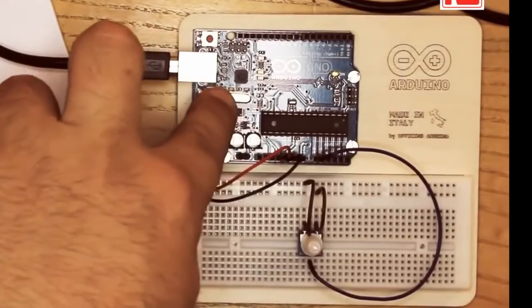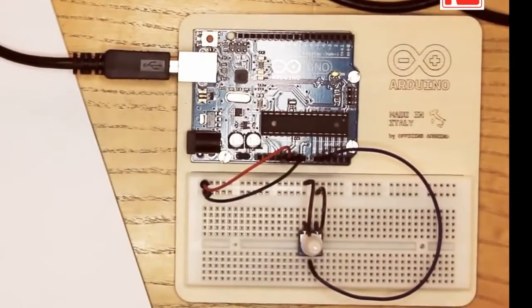So we're going to be using, for this project, something that's called serial communication, because the Arduino will send data over to the computer 1 bit at a time at a certain speed that we will define in software. And then the square chip that you see here will convert that into USB data that travels over to the computer. We have used serial communication in the past in order to visualize the data that comes from the Arduino board within the Arduino IDE.